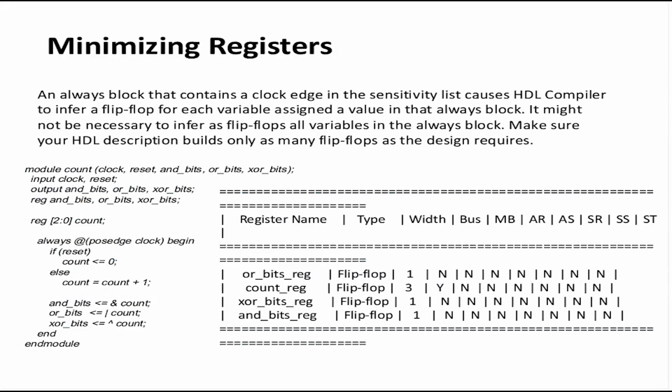They represent a timing sequence and the way you code the RTL. So you have to make sure that your RTL contains sequential elements only when desired. It's the duty of the designer to make sure of that. If you have unwanted sequential elements, obviously your area will be more.